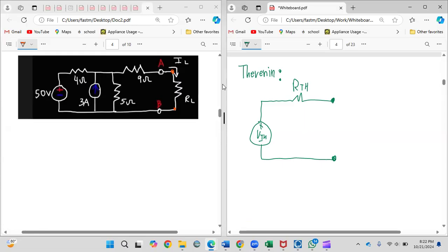So you have the entire circuit reduced into a resistor and a voltage. When they say reduce the circuit into its Thevenin equivalent, that's the way to find the R Thevenin and the V Thevenin, or the Thevenin voltage. And this part here is just where you're putting in your component that you want to manipulate.